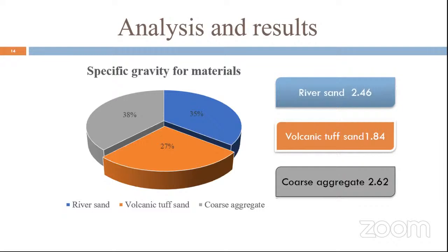Okay, yes. I mean, when you put a chart that summarizes, a graphical presentation, it attracts people. But somebody will try to understand the logic behind that. Because what I know, with the specific gravity of material, you are just characterizing the aggregates, and then you can see what the typical range is. You want to know whether your material satisfies it.